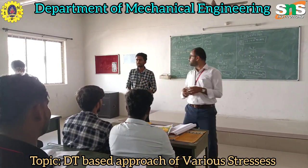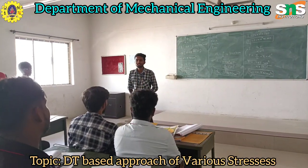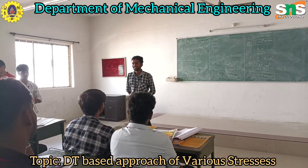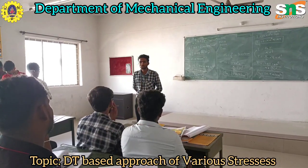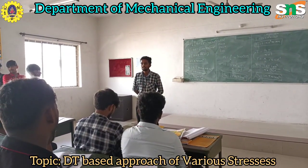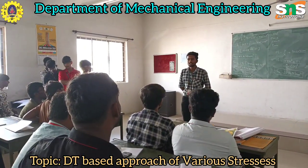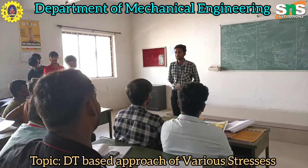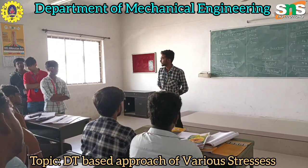Direct stress is the type of internal stress which is produced in a material or an object when it is subjected to an external force. It is of two types: tensile stress and compressive stress. Tensile stress is produced in the object with tension, and compressive stress is produced in the object with compression. The formula used is force by area.